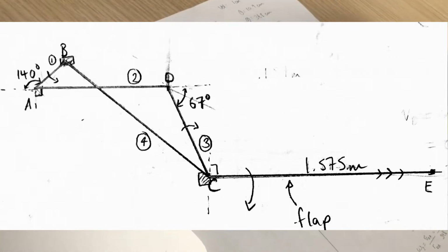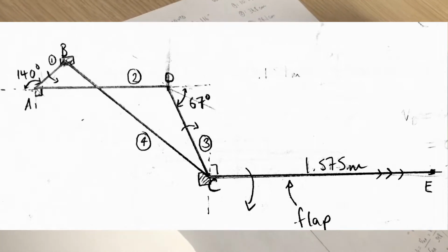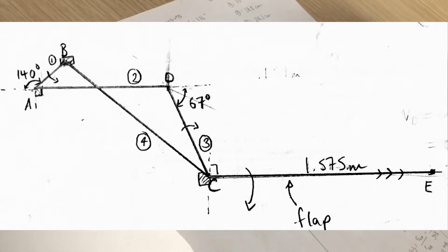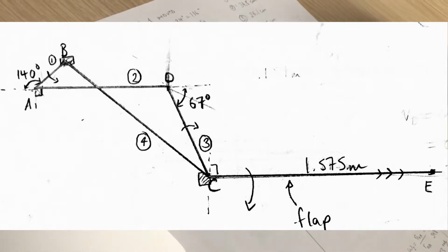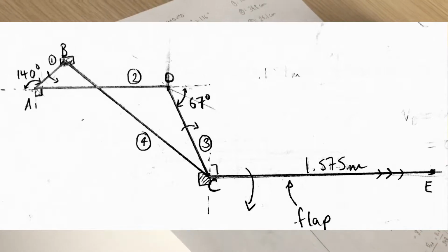To begin, we treated the wing flap mechanism as a 4-bar linkage. Link 1 is the driving arm of the mechanism. All of the movement begins from this link. Link 4 acts as ground. This means that points B and C are stationary and have zero velocity.